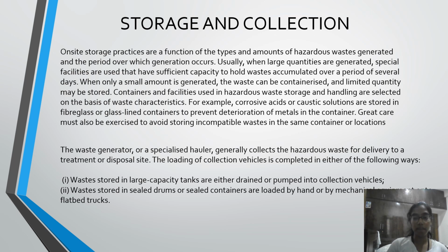When the waste can be containerized, an unlimited quantity may be stored. Containers and facilities used in hazardous waste storage and handling are selected on the basis of waste characteristics. For example, corrosive acids or caustic solutions are stored in fiberglass or glass-lined containers to prevent deterioration of metals in the container. Great care must also be exercised to avoid storing incompatible waste in the same container or location.